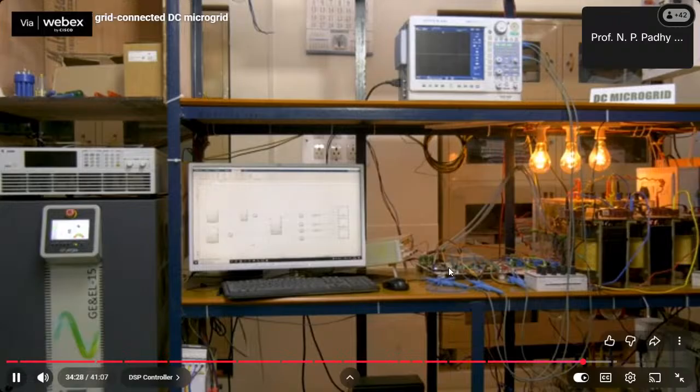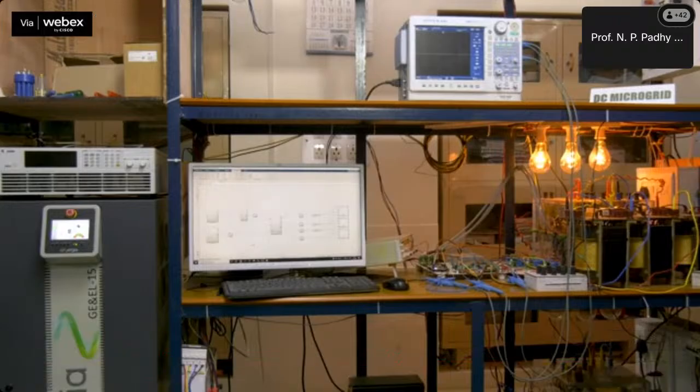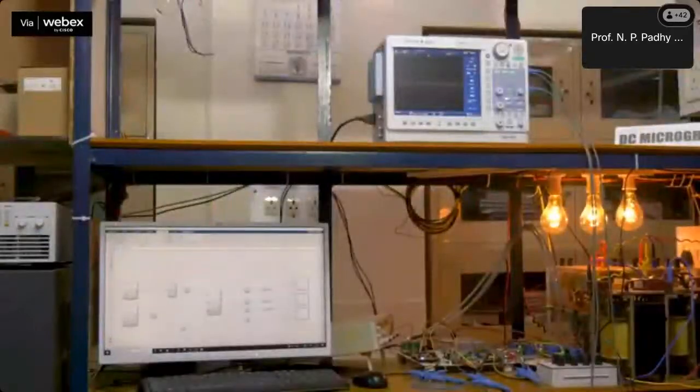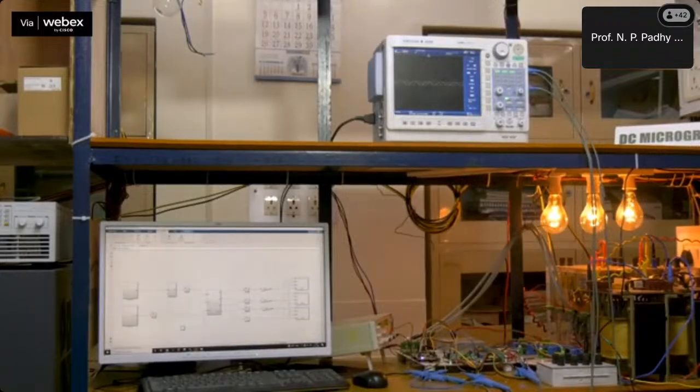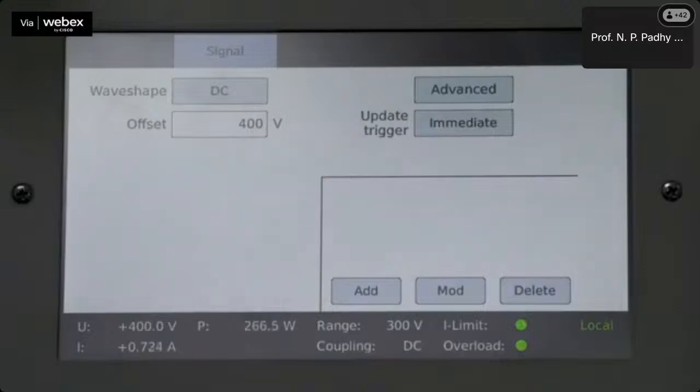Now the low power circuit and high power circuits are powered up. Now it is time to enable the control loop. The control loop is enabled, and by observing the DSO, there is power flow between the DC bus and the AC grid. Observing the power amplifier shows the power sign positive. That means it is giving power out, that is, the power is flowing from the DC bus towards the AC grid.